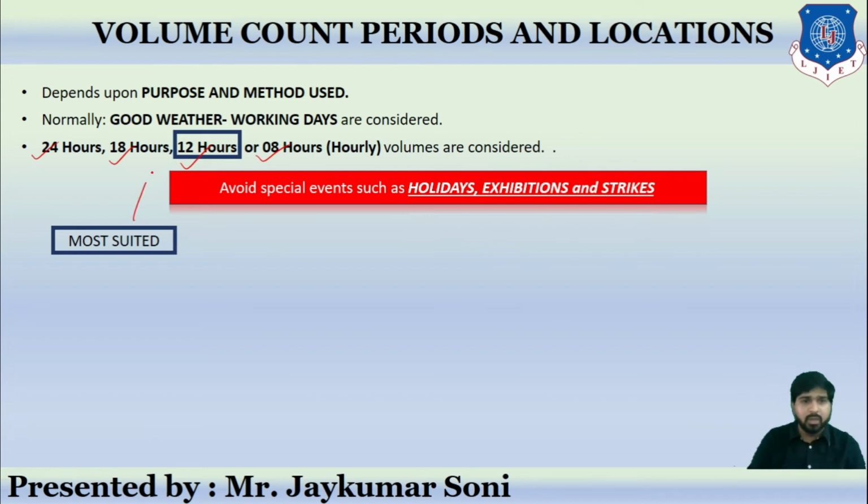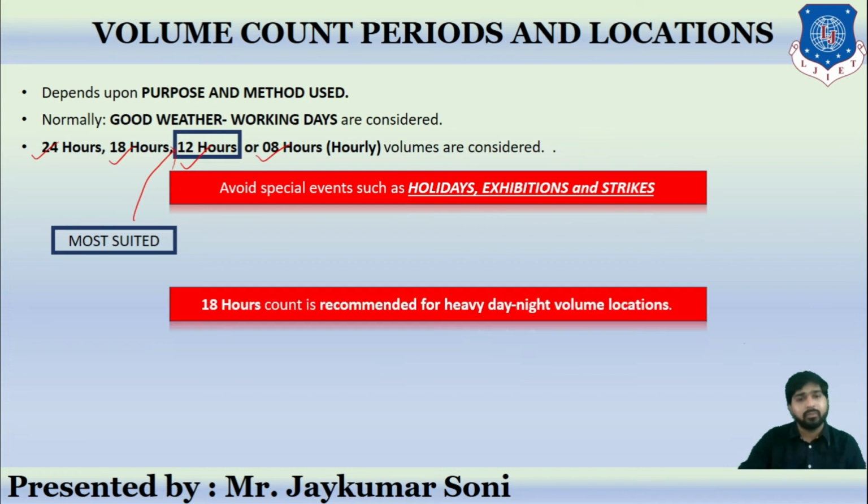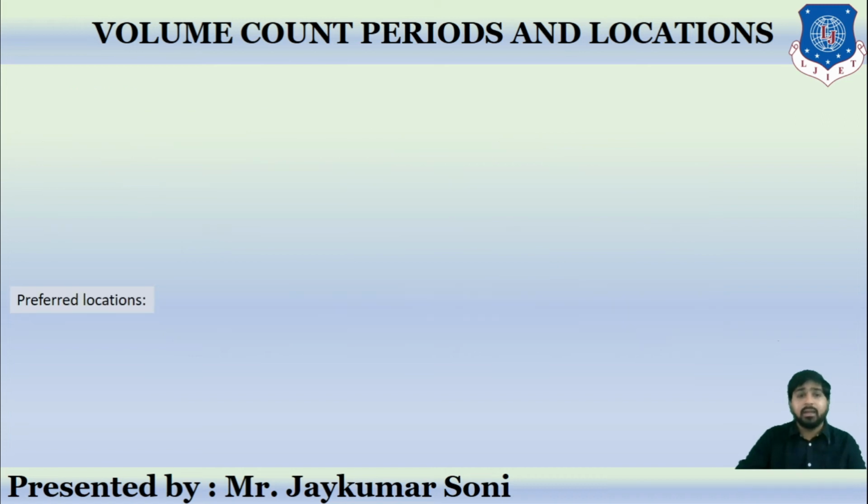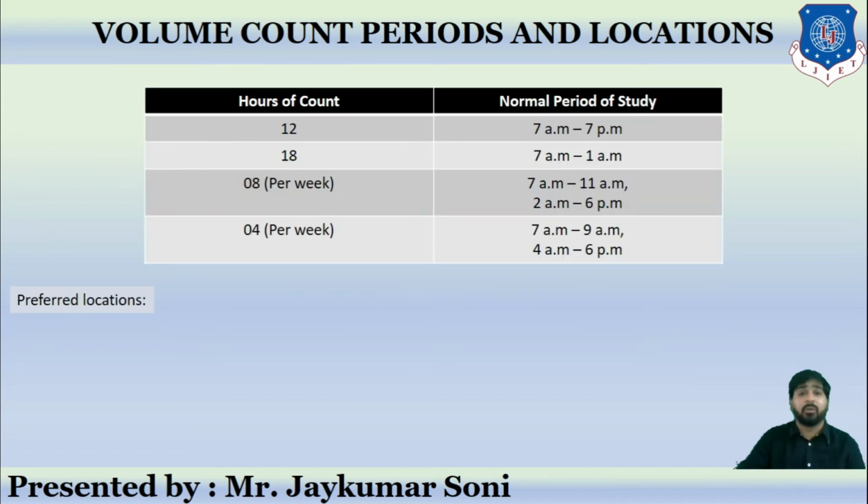The most suited duration is the 12-hour survey. An 18-hour survey is also recommended when there is heavy day-night traffic volume, means on express highways, on national highways. At that particular location, we need to have a survey of 18 hours. Now, where do we conduct these surveys?